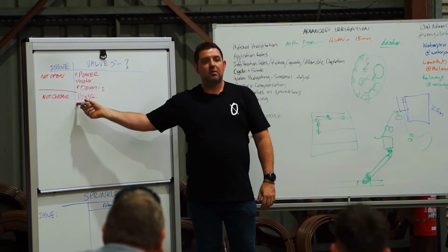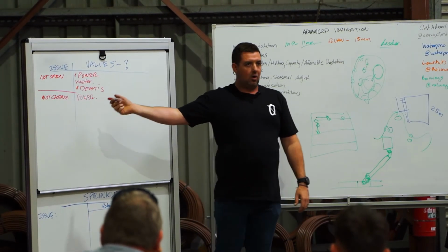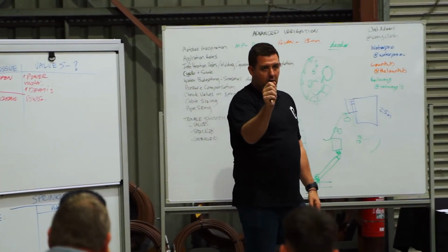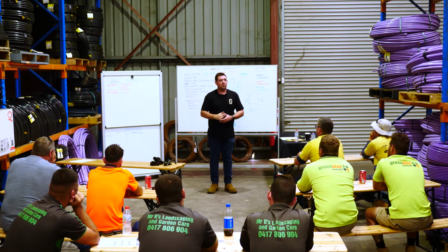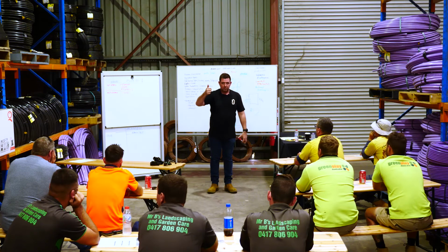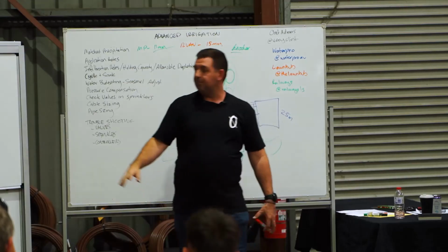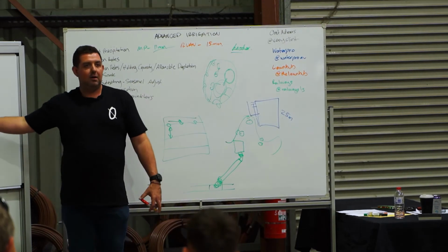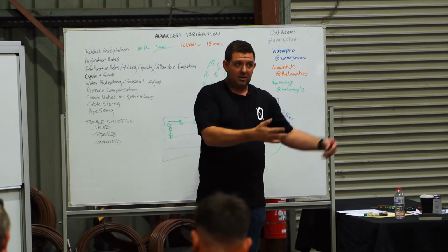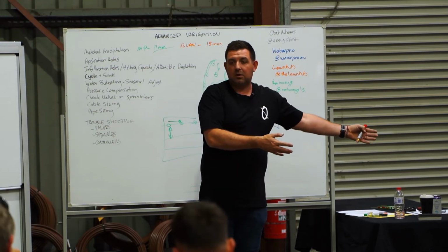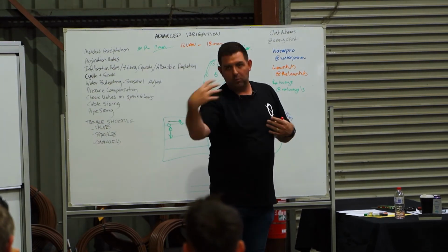So to troubleshoot that, if it's not turning off, you can turn the controller dial to off, or worst case, if the client is on the phone to you, flick the power at the switch to the controller. If the power at the switch goes off and the sprinklers pop down, you know that it's power. That will give you the ability to say to the client, look, is it really important that we fix it now? Obviously it's just watered. Can I come back when it's not midnight Sunday and we'll look at it?